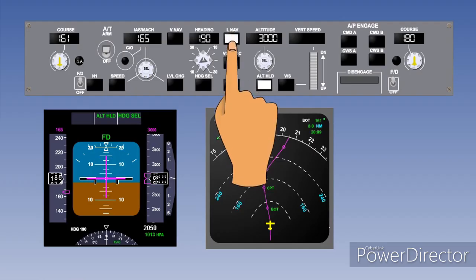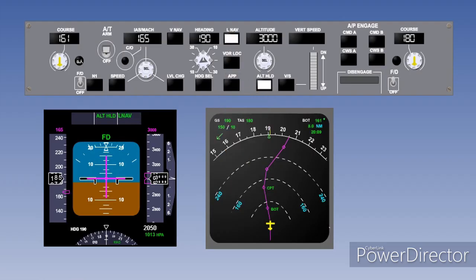The other way to set up lateral navigation is by using LNAV, which utilizes the Airways Track database in the flight management system. The flight director computer, using a combination of inertial navigation and global positioning systems, and the selected track from the flight management system, sends commands to the primary flight display, so the pilot can follow the selected track. This system can be used all the way, from pre-departure until arrival at the destination. LNAV mode is displayed on the flight mode annunciator in green, with the actual track being displayed as a magenta line on the navigation display.